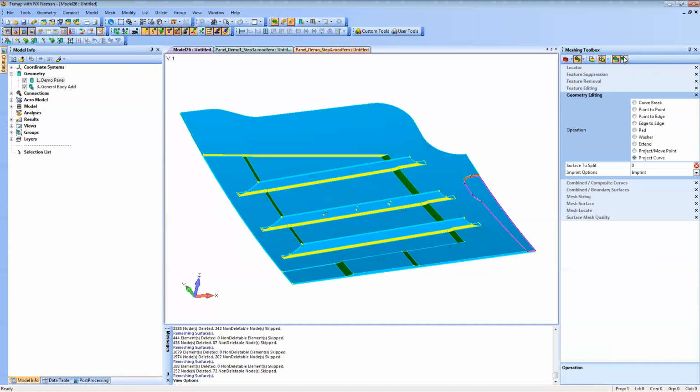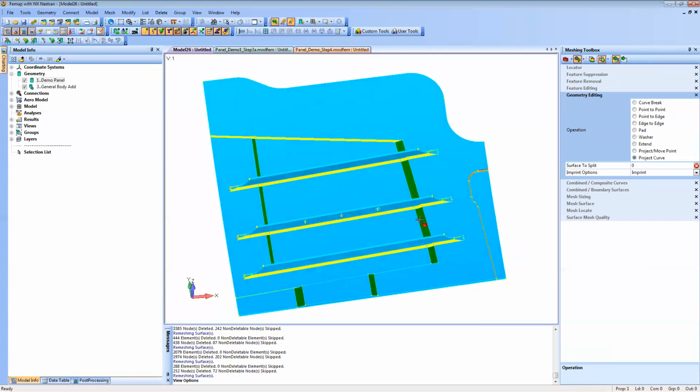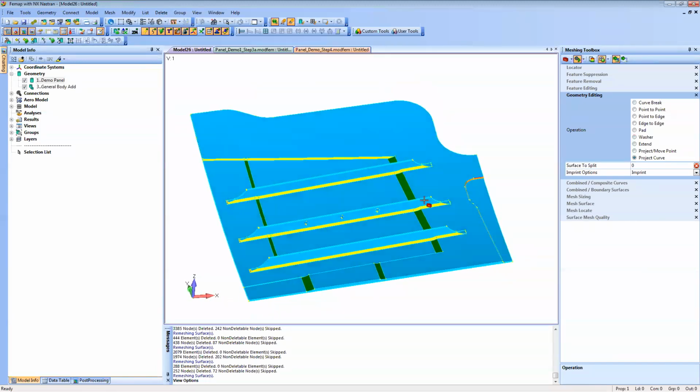And then what we've referenced a couple times is Tommy did an add tangent surfaces where we picked one surface and could add everything tangent to that. In the next version of Femap, which again should be coming out any day now, there's an option to do that on curves too, or edges. So if you have tangent edges, you could select a bunch of tangent edges all at once. So that'll be pretty cool to have as well.